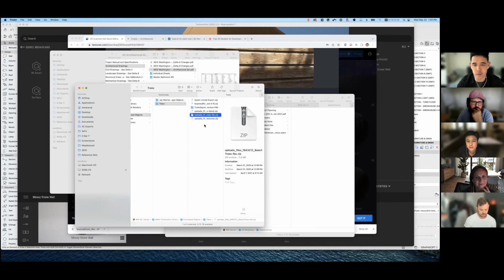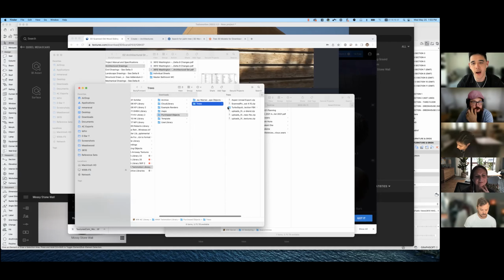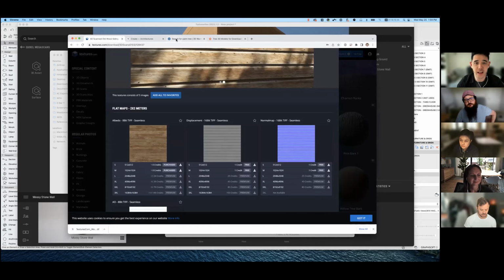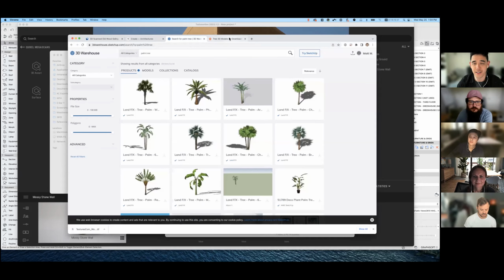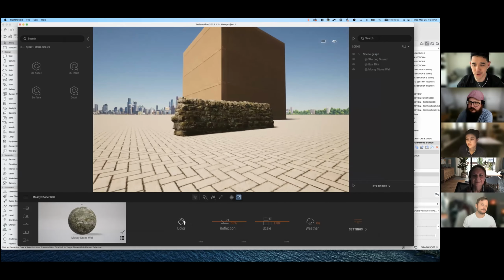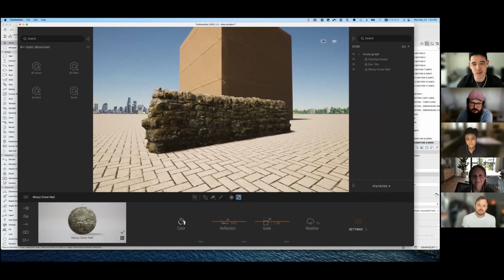All the trees that we've purchased, we place here, so we can flesh this out. Especially with trees, you really have to watch the file size. And again, you'll know if it's too big because it'll blow up your file and you'll want to undo it. But most of these things you can download in different sizes. So it's a work in progress.